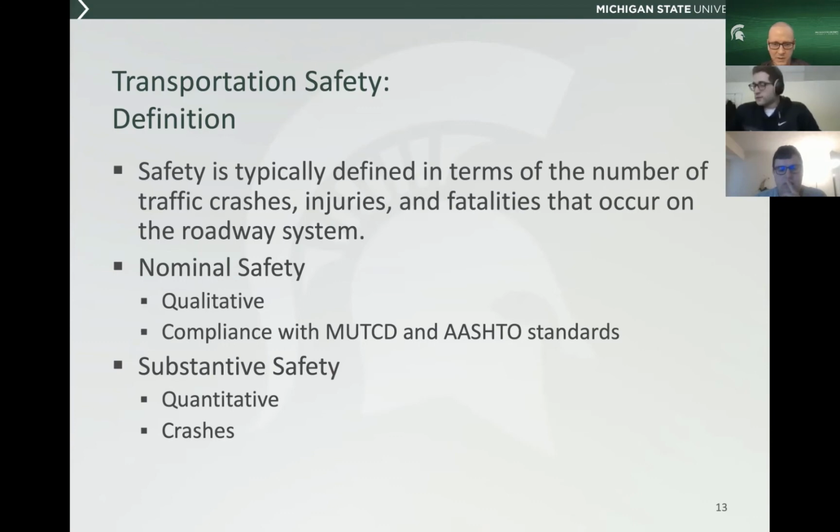Okay, so you probably had some exposure to what we refer to as crash modification factors and safety performance functions. And so we really have a suite of predictive tools that have been developed by research to help us use an approach that's more data-driven and quantitative in nature. Because if you look at the field of safety historically, and this is still true by and large today as well, we tend to make investments and introduce safety improvements at locations that have a documented safety problem or series of safety problems that have a crash history, basically, right?